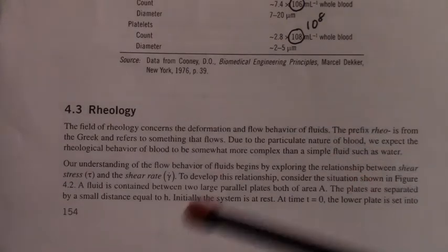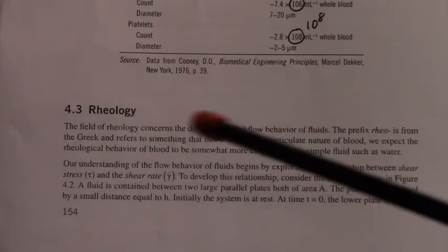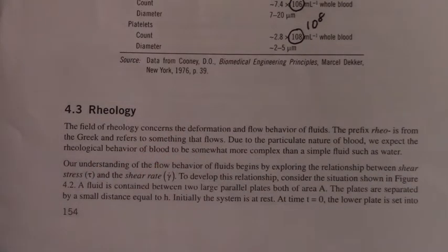And our understanding of the flow behavior of fluids begins by exploring the relationship between shear stress and the shear rate. Now, I just talked about shear rate being the rate of deformation of the deck of cards, and the shear stress, remember, is a force acting parallel to a surface. So if you took the force that you applied to the deck of cards and divided that force by the cross-sectional area of the deck of cards, that would give you the shear stress. And then the shear rate is the rate at which the cards deform.